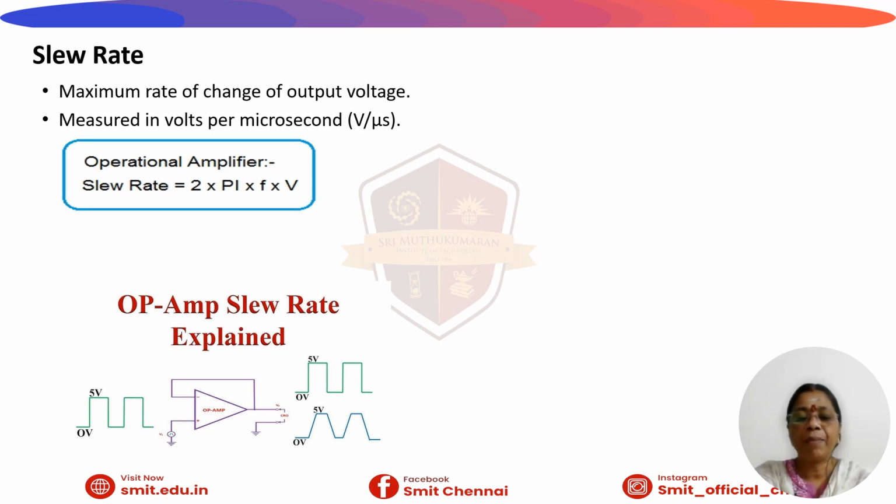For a sinusoidal signal with peak voltage Vp and frequency f, the minimum required slew rate to avoid distortion is calculated as slew rate equals 2 pi f into Vp. So f refers to the maximum frequency.